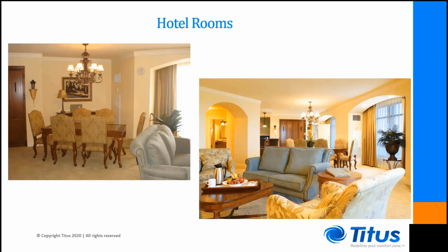Here we show a much nicer set of pictures showing a completed installation of two standalone vertical stack units that have been installed in sheetrock walls. In the left picture, it is a little difficult to see, but in the back right corner of the dining area, we can see the standalone vertical stack unit installed. At the top is a rectangular white supply grill sending conditioned air into the occupied space. Below that is the unit's thermostat, and below that a white access return panel. This panel is louvered to allow return air to enter the unit through a filter. Also, all maintenance and servicing of the unit is done through this panel.